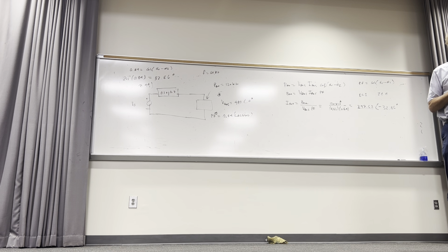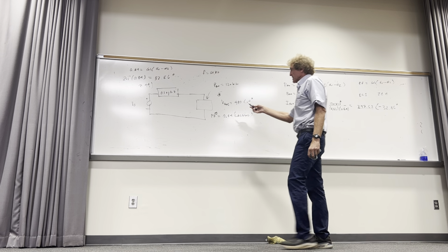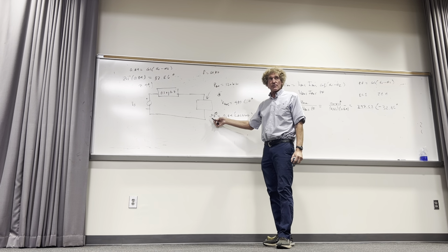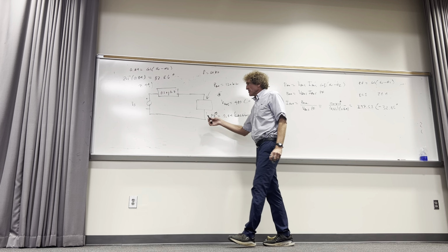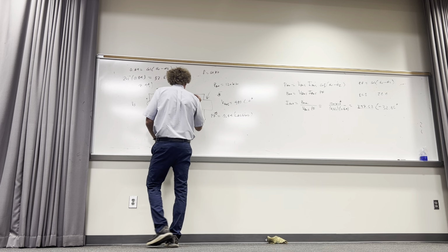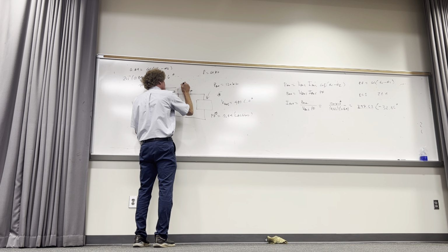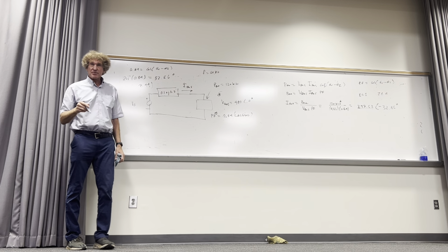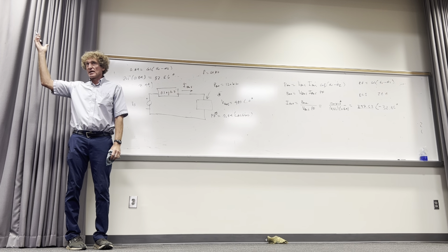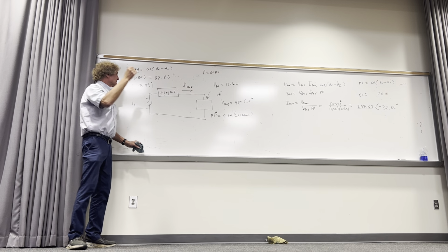Now what we're going to do is get the voltage at the source. Ask yourself how I would do that. Well, I have the voltage here, correct? I have 480 at 0 degrees, both angle and magnitude, right? But I don't have the voltage here. But now I have the actual current, IRMS, don't I? Both magnitude and angle. How many see that? And therefore, I can get this voltage.